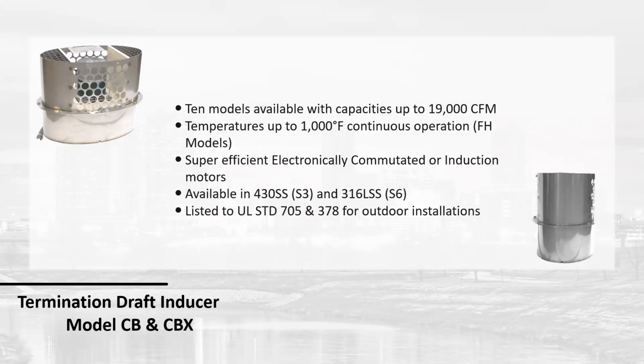Again, EC or induction motors, depending on the size. All of our products are available in stainless steel. Most of what we sell is in 316L. It's an alloy that can handle the corrosiveness of condensate. But if you're in a system where it's a category 1 or it's a steam system, very little chance of condensation, we can drop down to that 430.